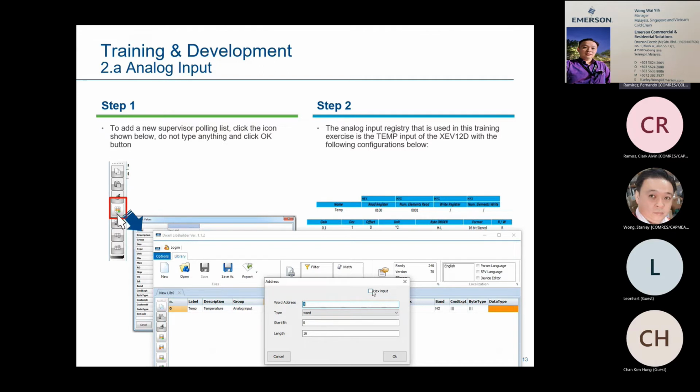So you have to set it up as a hex input. Just type in 0100. Please be careful with this one because other devices might use decimal instead of hex. So just make sure that you look very carefully at your Modbus register list.